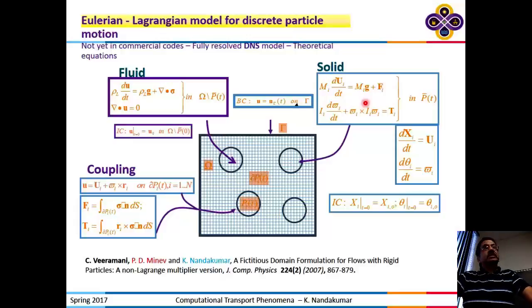But their density is considered, because it is the density difference between the solid and the fluid. See, density appears here for the liquid, and the density appears here for the solid. The density times volume is the mass, right? It will appear there. It is that one that's going to cause the particle to move down or up. If they are neutrally buoyant, then they will cancel out.